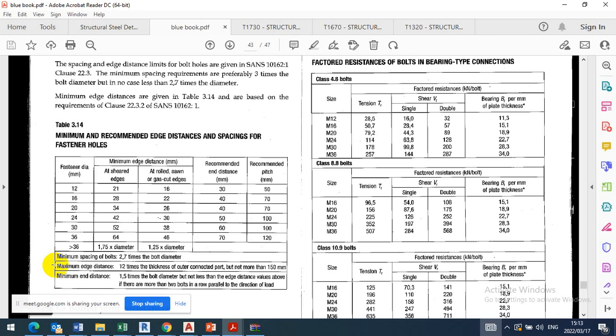Then you need to say 50 divide into 200 megapascals. Then you know how many bolts you need. It goes to you knowing how much force is coming to the beam and knowing how much one bolt can accommodate. Yes, once you know how much the force one bolt can take, then divide that amount into the total force coming to the connection. Then you know that I need 3, I need 4. Of which size? Then you go into determining the size of the bolt.